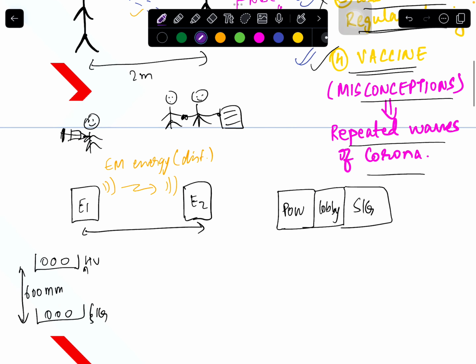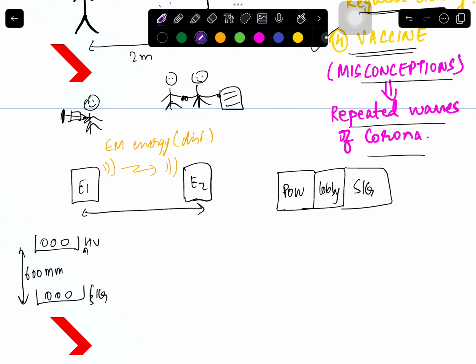So basically what we are doing is, if we are reducing this segregation to 300, we are saying okay, protect, wear mask. So we are providing a cable tray cover on top in order to help us from getting affected from the HV cable. So anything that could have come and affected us, we are now protected because we have shielded ourselves.